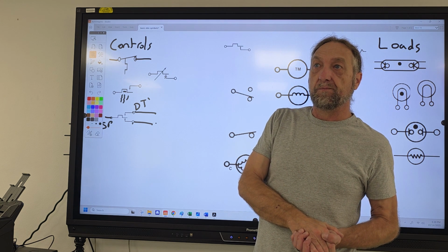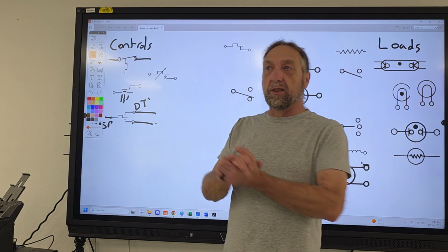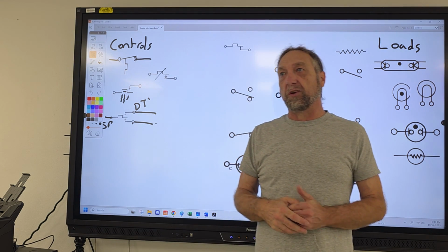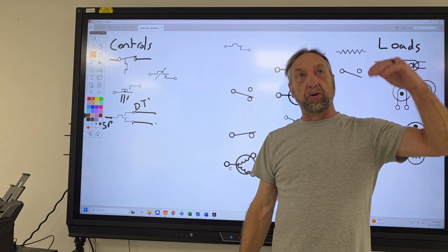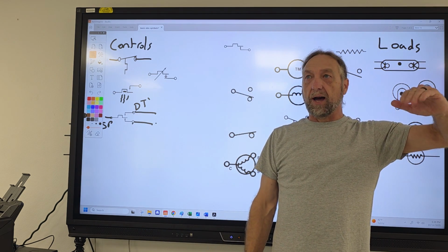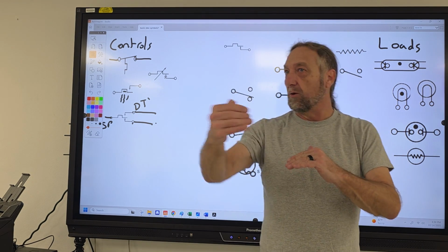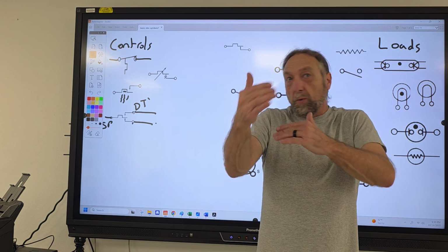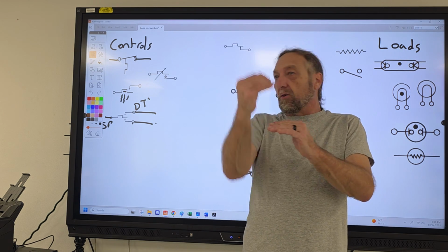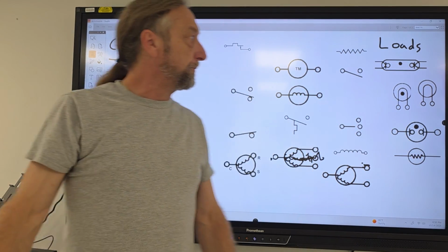So what about when they ask you high, low? High-low is just the actual magnetron that's producing heat. On high, it's on 100% of the time. If I put it on anything less than high, the magnetron comes on, goes off, comes on and goes off. But whenever it's on, it's full power, and when it's off, it's off. So it cycles on and off so it doesn't overheat the food. The same thing for a toaster.